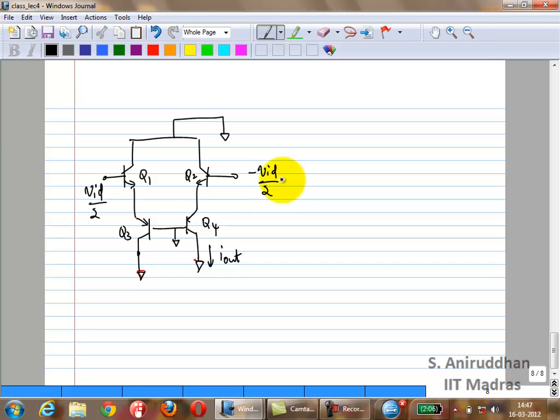I see some of you didn't bring your notebook. So you take one half side, draw the equivalent circuit for that. Now for calculating the transconductance, neglect R out. That's what we've always done, even for the MOSFET. That's the easiest way. When you're calculating transconductance, you short the output, neglect R out. When you want to calculate output impedances, you take R out into account.